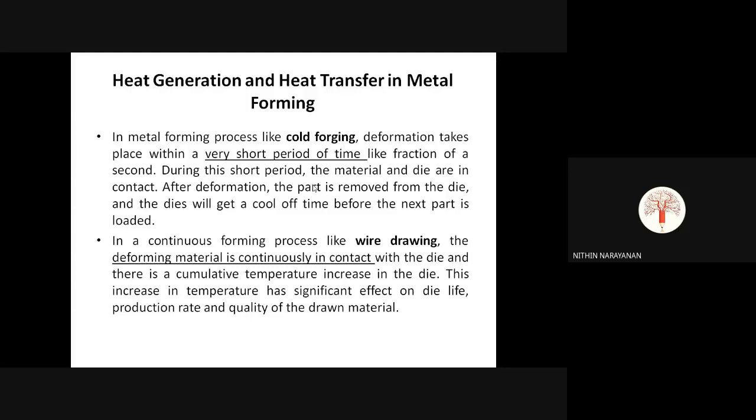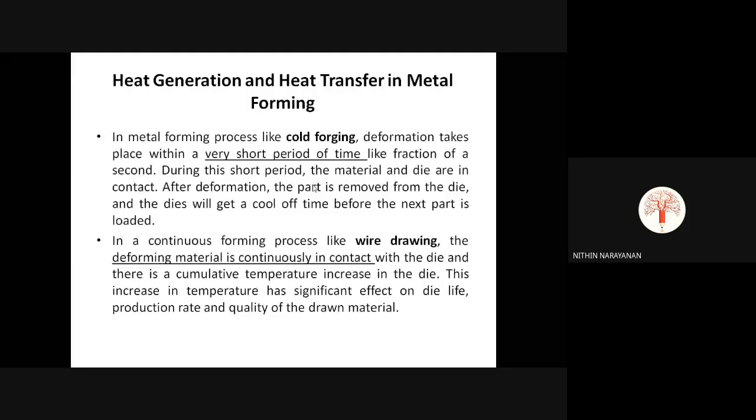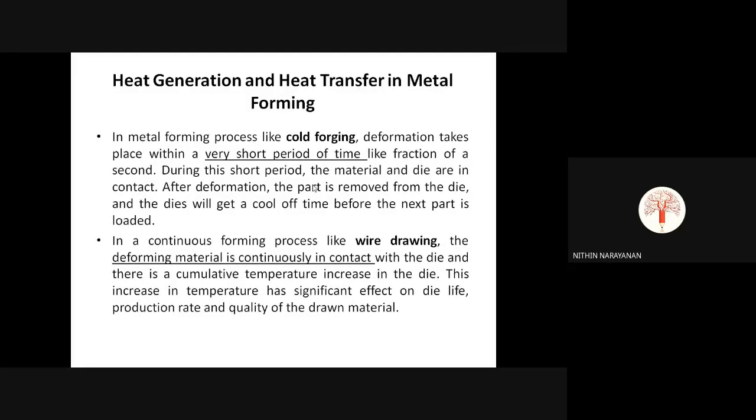After deformation, the part is removed from the die and the die gets a cool-off time before the next part is loaded. So here we need not consider the heat transfer between the die and the material, because in cold forging the deformation takes place within a very short period of time, like a fraction of a second. During this short period the material and die are in contact, so the heat transfer rate into the die will be low. After deformation the part is removed from the die and the die gets a cool-off time before the next part is loaded.